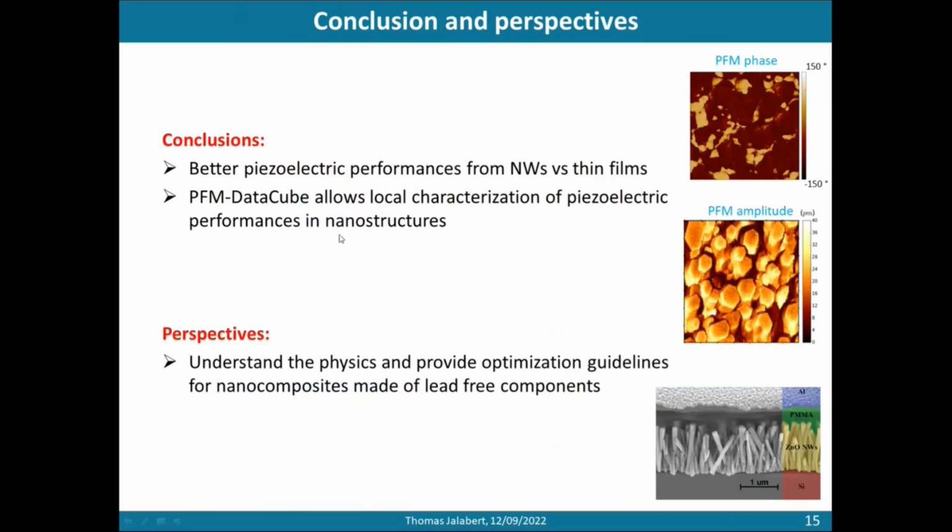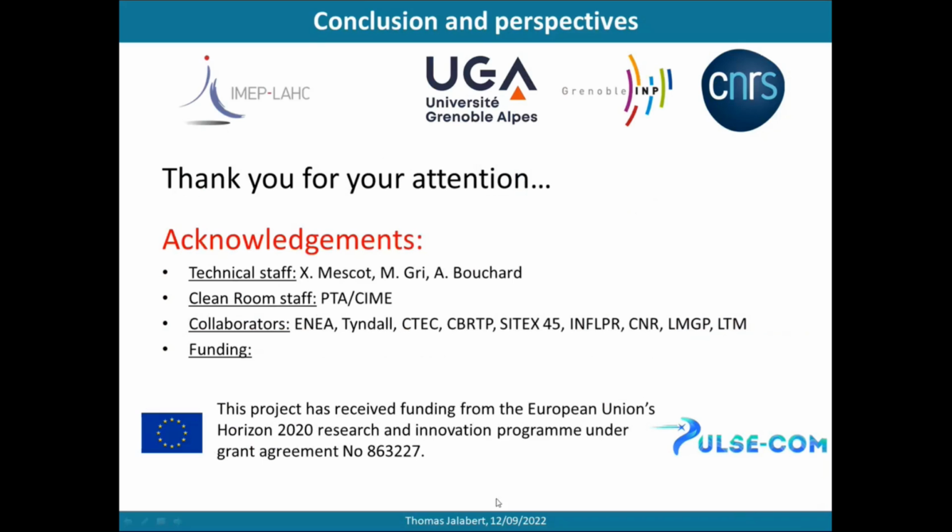To conclude, I hope I convinced you that nanowires have better piezoelectric performances than thin films, and that we have what we call a PFM detection method, which is a technique that allows local characterization of piezoelectric performances at the nanoscale in this kind of nanostructures. And this PFM technique allows us to better understand the physics and provide optimization guidelines for the nanocomposites, such as vertically integrated nanogenerators. With this, I would like to thank our technical staff and all our collaborators. And I also would like to thank you for your attention.